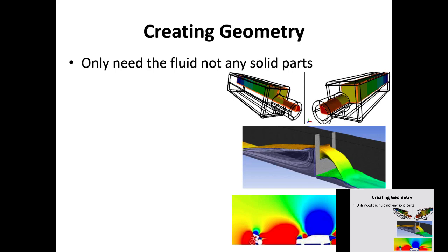Okay. So for example, you have a pipe. If there is a pipe and there is a flow inside the pipe, you don't take the pipe thickness into account. You don't. Okay. You only look at the fluid inside, the diameter of the fluid continuum inside, the diameter of the fluid volume inside. That's what you look at, and you are modeling only that.